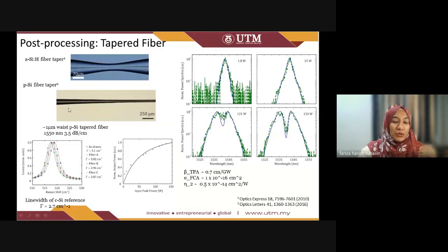By doing so, because when we taper the optical fiber we supply heat to the materials, the core will slightly be molten again, and as we stretch out the optical fibers, we can rearrange the crystalline orientations of the silicon materials.